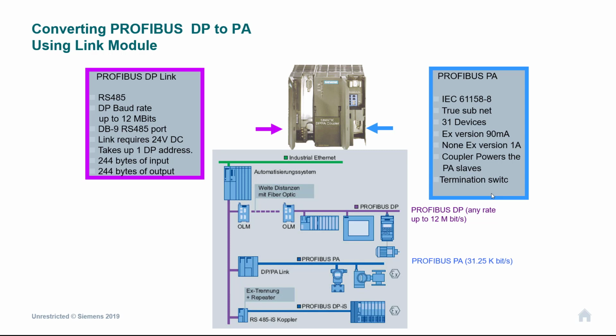So you do need to leave some spare capacity. But straight away you can see with this EX version that if I'm drawing 14 to 15 milliamps, I'm restricted to no more than probably 8 or 9 instruments on that one network. Definitely not 10. So I would have to add another EX coupler. Now I can put, I think it's up to 7 EX couplers on one link. Okay, but I've still got my 244 byte limit.